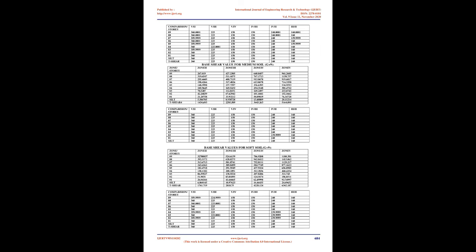In tall buildings with large height to base size ratio, the horizontal movement of the floors during ground shaking is large. In short but very long buildings, the damaging effects during earthquake shaking are many. In buildings with large plan area, the horizontal forces can be excessive to be carried by columns and walls.